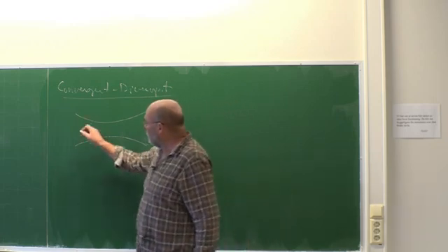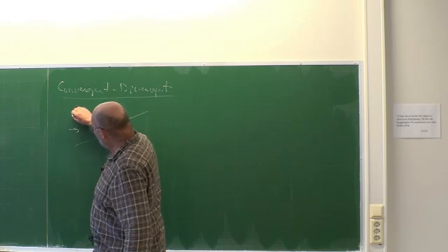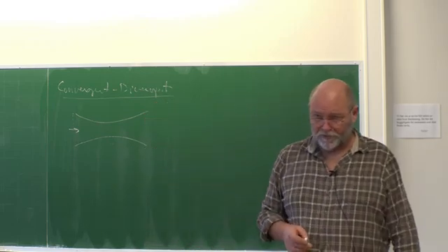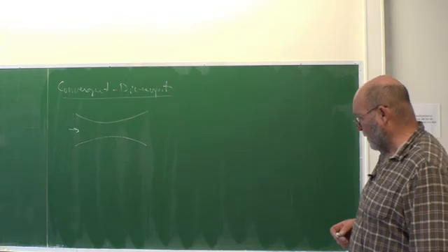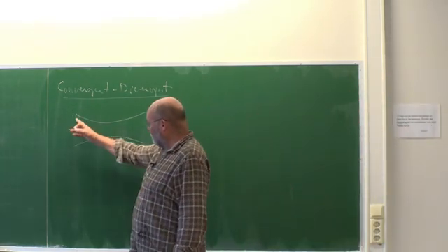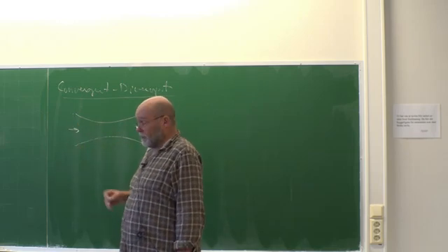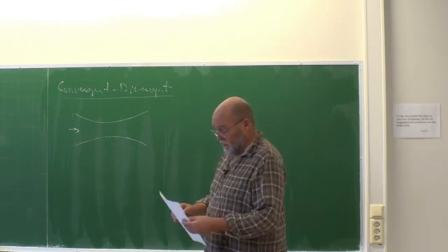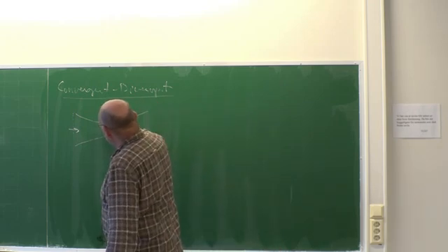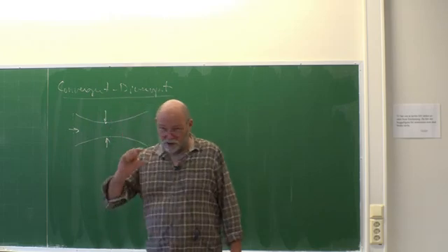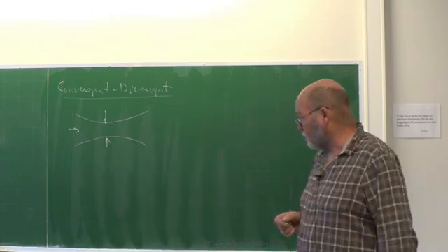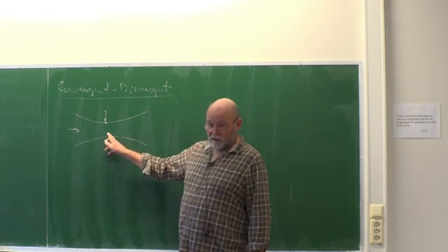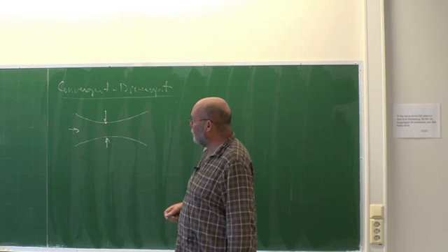And then here we will sort of have our inlet. Actually it should be the reservoir, but we can't simulate an entire reservoir, so we cheat. We create some inlet values there. Constant pressure. And the velocity then has to find itself a value there from the solution. Fair enough. And then here you sort of have the narrowest opening where the area doesn't change anymore. So that's the location we can find Mach 1 if the driving force is big enough.